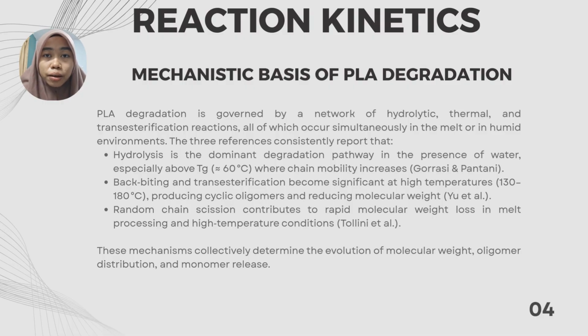I'm Farhana and I'm going to continue our presentation with the reaction kinetics part. So PLA does not degrade through one single reaction. Based on Gorrasi and Pantani, the dominant pathway is hydrolysis, especially above the glass transition temperature where chain mobility increases.